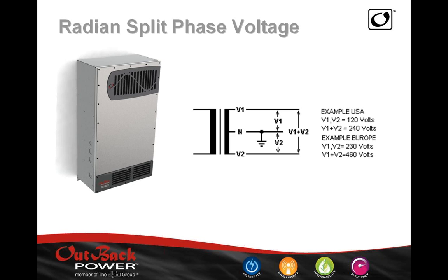The issue with that is that the phases are going to be 120 degrees out of phase. They're not going to be 180, and because the inverter is fixated around the 180 degrees, it's not going to accept the AC source. So it's very important that we qualify the source beforehand.